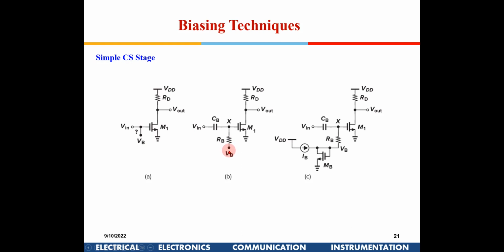How do I give a bias signal? I give a reference voltage here, I can give MB here, I will generate out one here, and I give an RB here, so I will get the DC voltage out here, right? And then I give an AC signal. So this is biasing a simple CS amplifier. Can somebody think of a reason why this RB is required?